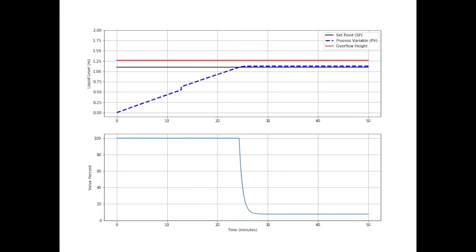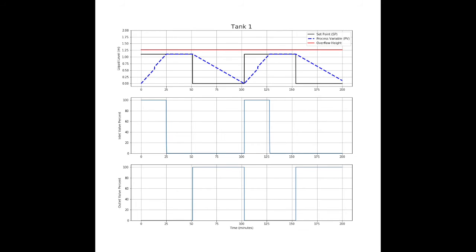We used the Kc value found in the FOPDT model to model our P controller. Ultimately, we set up a logical P-controlled system. The logic portion of the controller allowed us to fill one tank while the second tank empties. It also allows us to add a delay time to achieve complete mixing. Ultimately, we only needed the P portion of the controller because it was an integrating system.